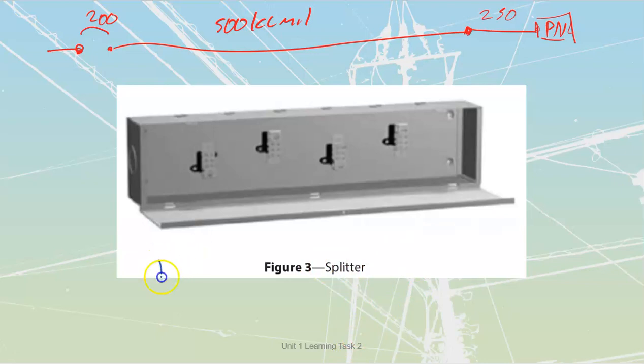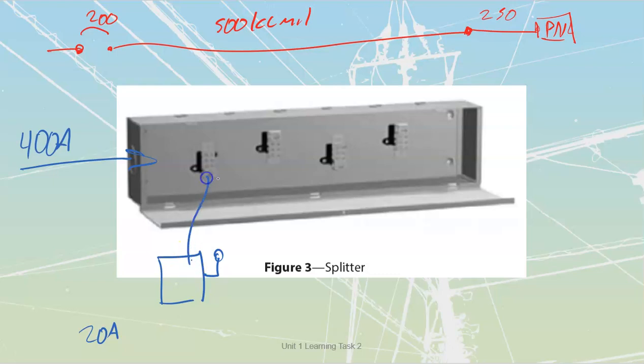This would be if I have a splitter, and maybe feeding into the splitter I'm going to have, we'll call this thing 400 amps. Then dropping out of that splitter, I've got a whole pile of smaller disconnects. Now, if I've got 400 amp wires, that's going to be twinned up 250s that we're going to be running into this thing. But let's say I've got a 30 amp switch that I need to feed out of that. Okay, I've got some sort of a load. Maybe the load is about 20-ish amps. So I'm going to feed that out of a 30 amp switch because that's going to be my next standard size. What I'm allowed to do is take 30 amp wire,